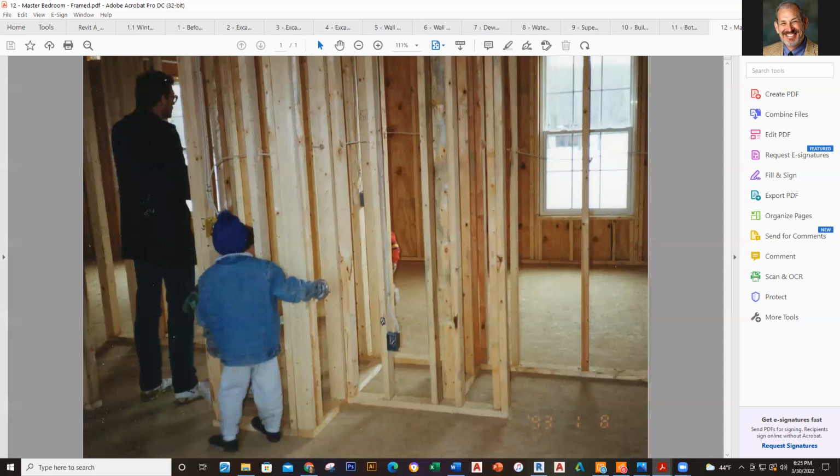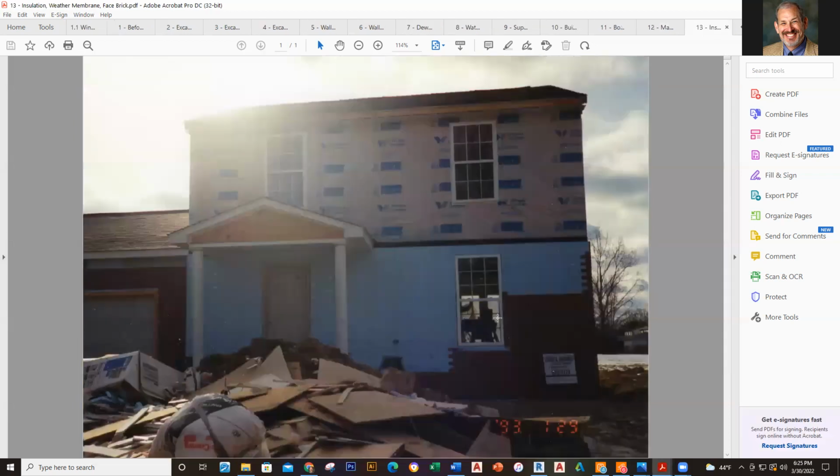Next, you see what it looked like once we began to put on the exterior finishes. Here's a shot of this particular structure, January 29th. The roof is on, and we began to put in this face brick. It's actually what they call brick veneer. This brick veneer was 3/4 inch thick brick material, the size of a standard brick. It got pressed into this blue styrofoam, which had clips on it. And it got glued in place. That's how that was put in.